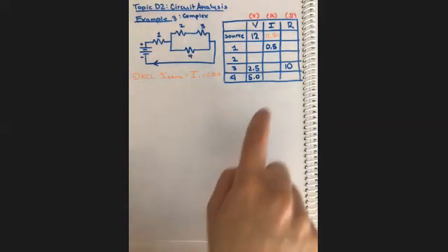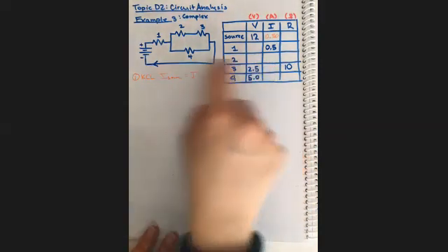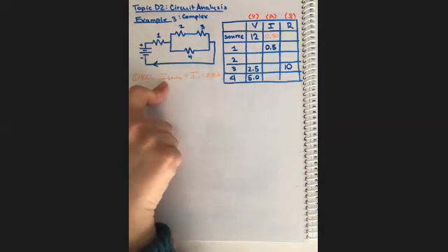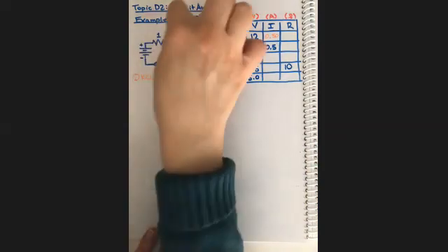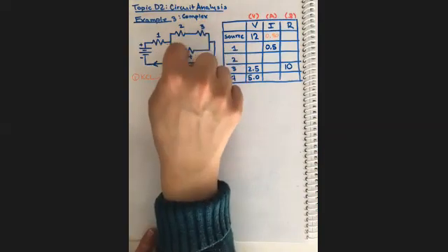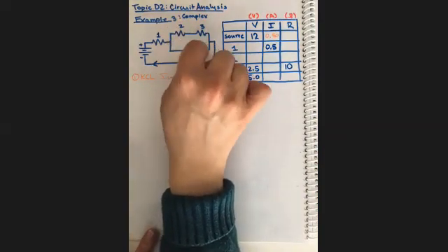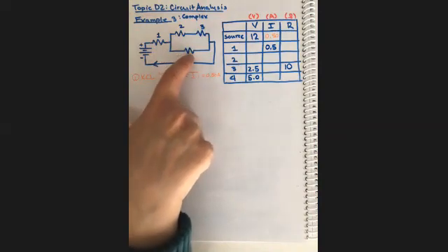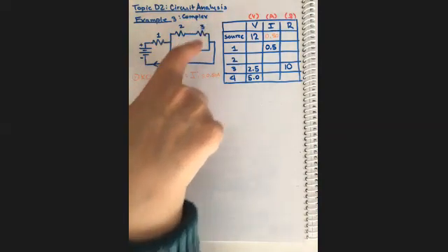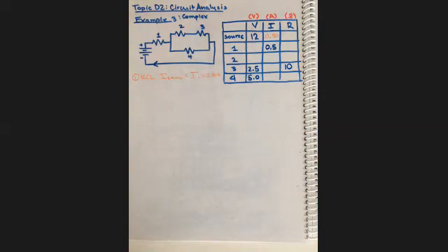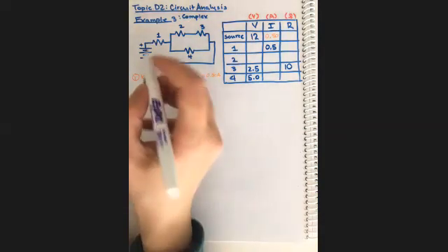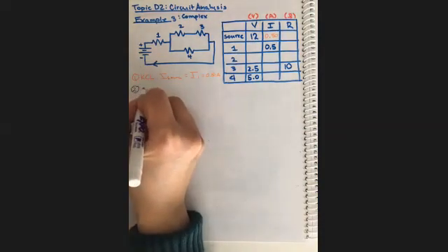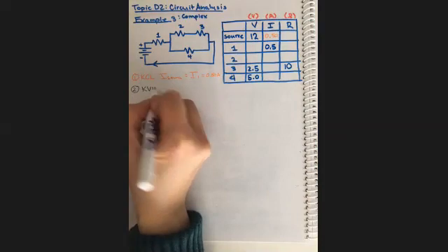Okay, so we could have started from Ohm's law. We could have started from where I did start. You could have also started from over here, knowing that the voltage across the parallel branches is the same. In this case, it's not V2 equals V4. It's V2 plus V3 equals V4. And that comes from KVL. So I think that's probably my second choice.